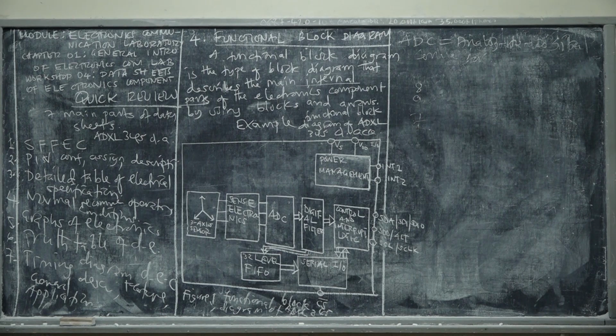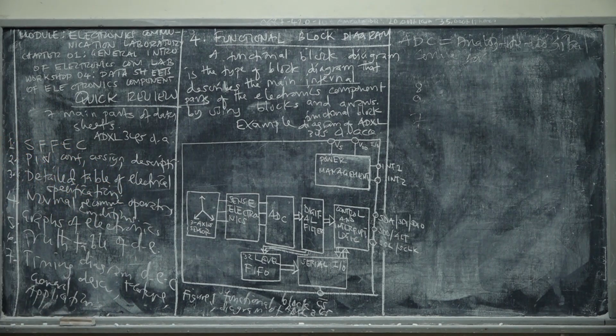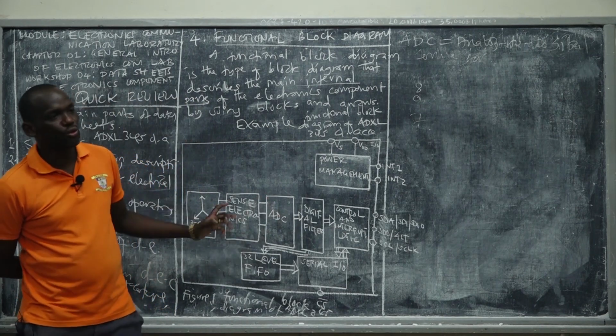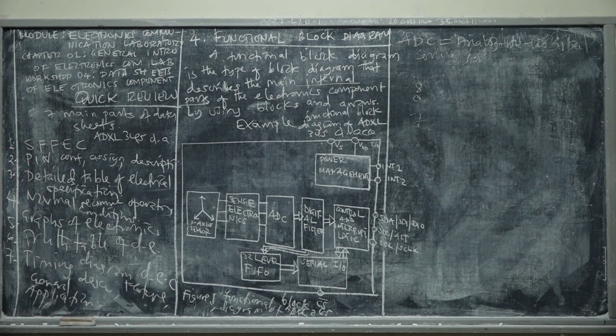But remember that the sensor is called a digital accelerometer, so the outputs expected to be fed to the control unit must be digital. The next blocks are digital blocks, they cannot process any analog information. They need digital signals, excuse me. Because the next blocks need the digital signal, we have to convert the analog signal which has been detected in either the x-axis, y-axis or z-axis. Those are the information that you have to get whenever you read a data sheet. Are we together?